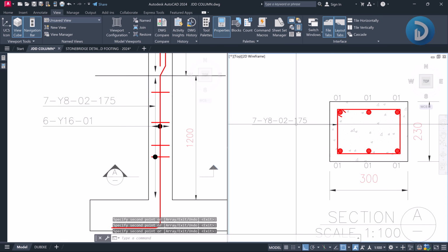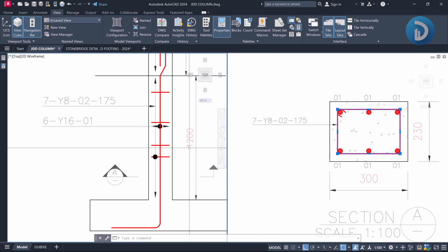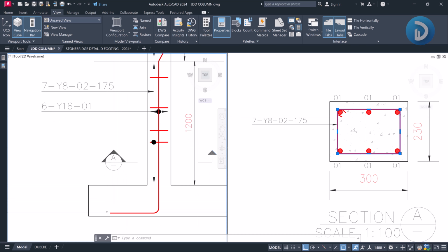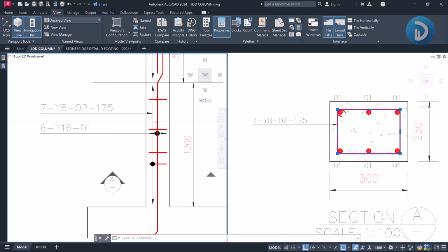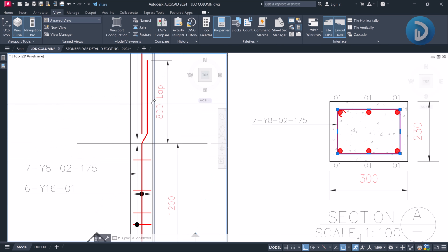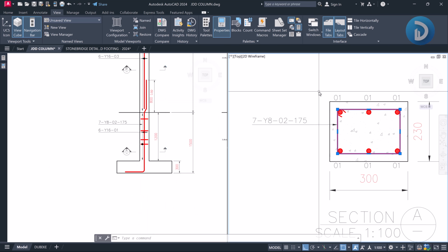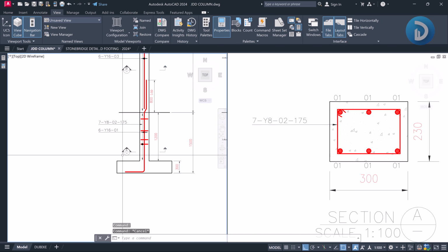Not just are they separated by the diameter of the reinforcement, they are also separated by the bent up properties. This will be bent in this way, like this, while here we have a development length, it will come up to the foundation level, and we have a crank length to receive the reinforcement at the ground floor level. Okay, so this is for the foundation level.